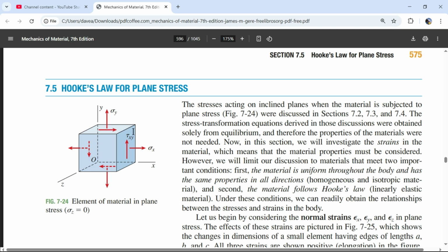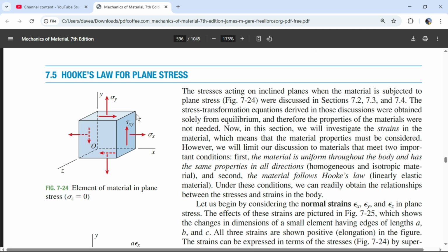Once we get those numbers and find those bigger maximum numbers, then we can compare them to the material, because the material can only handle so much tension, compression, and shear. So it can only handle so much compressive stress, tensile stress, and shear stress, and there's going to be a number for each of those given a material. Steel is going to be equally strong in tension and compression, but the number will be half for shear stress, for the PSI and shear. So given that, I thought that was a good way to go forward in this section.